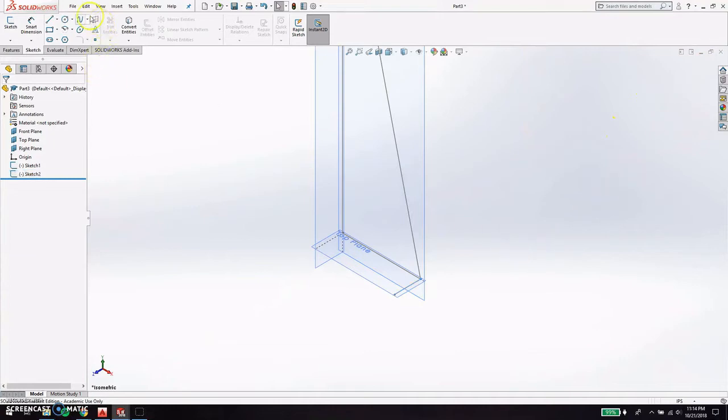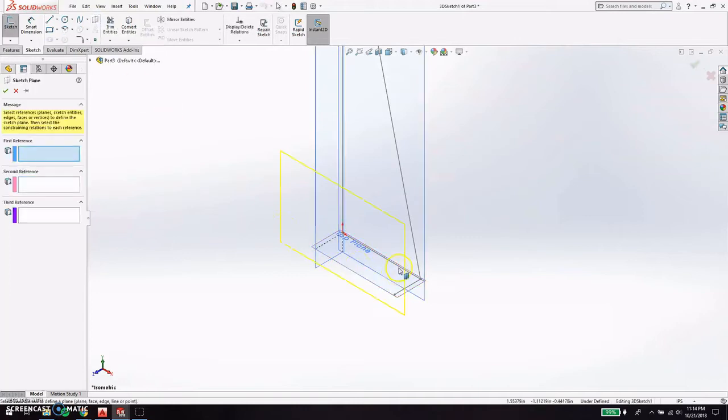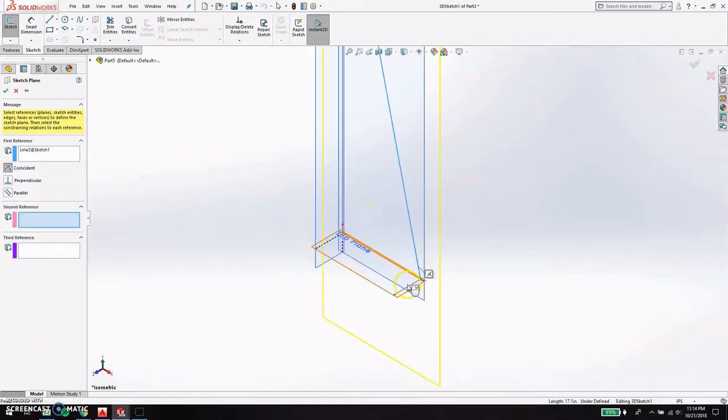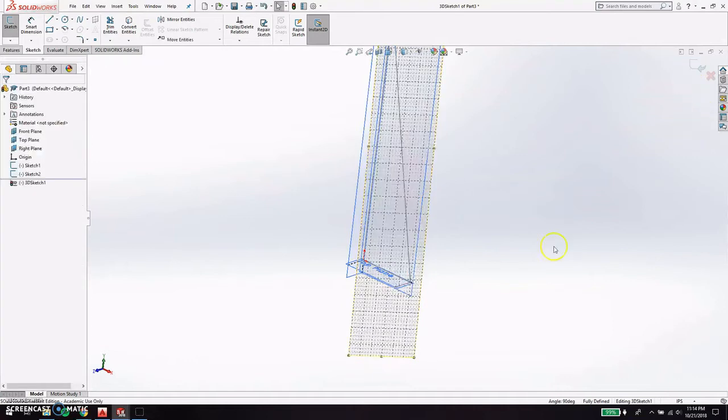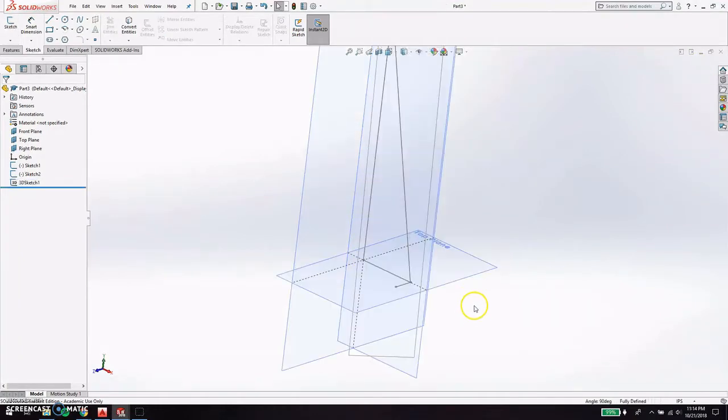That's great. Now click this plane right here. And it automatically just puts it somewhere. You can choose where it's going to include, and by clicking the two lines, and boom, you've got your plane. So if you want to make sure that this is the right one, yeah, you can see that this is encapsulating those two lines. And so there you go, you made a plane. So as you can see, you have to first finish your sketch, and then you got to load it back in. So now you've got this plane right here.